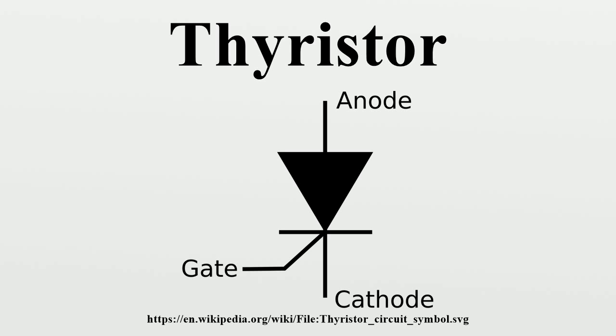A thyristor is used in conjunction with a Zener diode attached to its gate, and if the output voltage of the supply rises above the Zener voltage, the thyristor will conduct and short-circuit the power supply output to ground. This kind of protection circuit is known as a crowbar, and has the advantage over a standard circuit breaker or fuse in that it creates a high conductance path to ground for the damaging supply voltage, and potentially for stored energy in the system being powered.